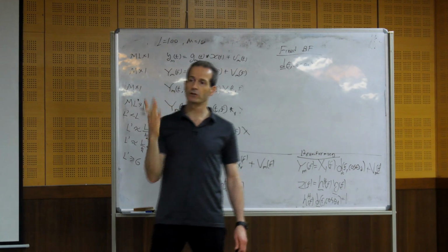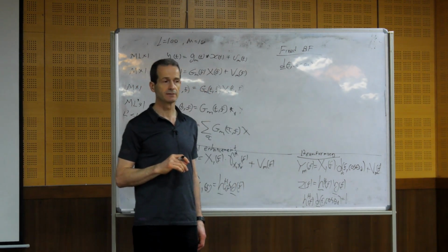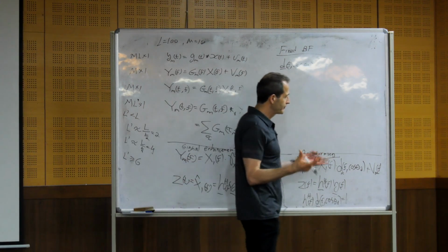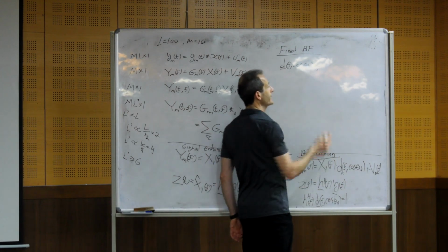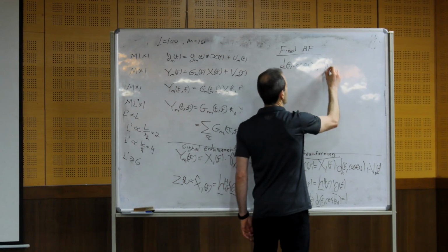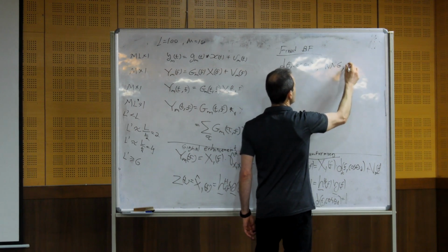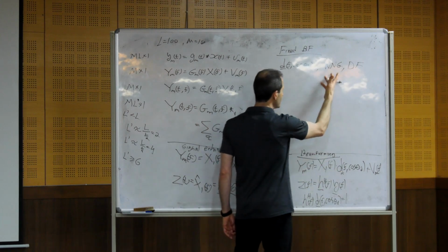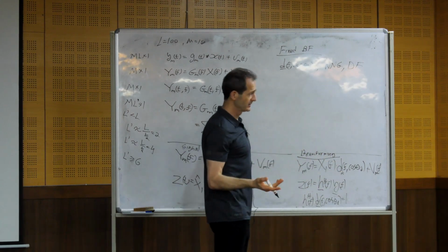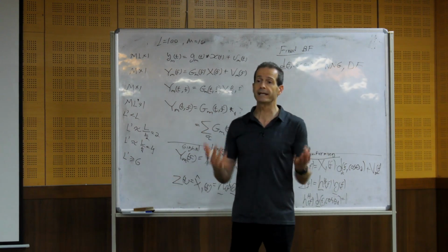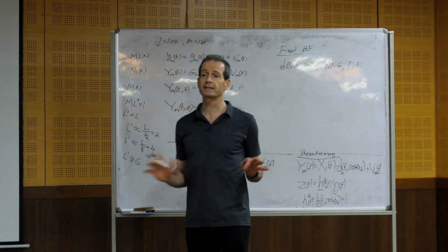So I know the direction of the desired source, and maybe some directions of interferences, but I don't know what type of noise, so I work either with white noise gain or directivity factor or a combination, which means that I assume that the noise is spatially white, or the noise is diffused, or a combination. Because I don't make assumptions about the noise.